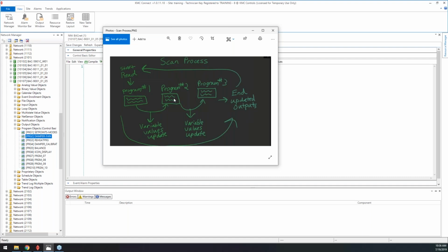It could be clockwise, counterclockwise for an actuator that I'm not allowing on at the same time, or it could be heating and cooling, or anything that I wouldn't want to be staged together. I can put that in the safety program to say, if output 1 is on and output 2 is on, then turn them both off, or just start output 1 and leave output 2 off. Putting that safety code in the last program protects me a little bit from doing something that maybe I didn't expect in the earlier programs.